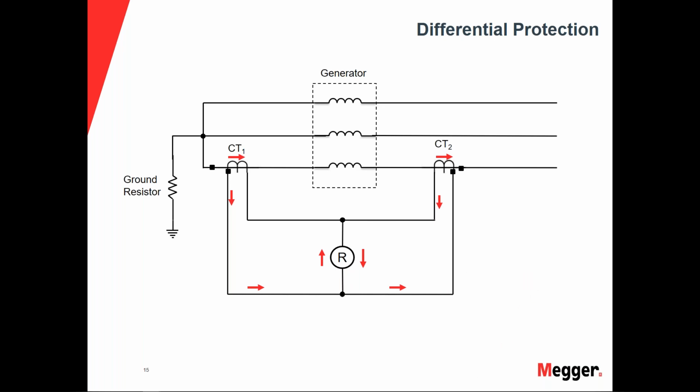When we do have an internal fault and the relay sees it, then this generator is going to be feeding into this fault. And when the generator feeds into the fault, we will get a reverse current coming back from the transformer or the unit or the breaker transformer combination over here, back into the system.